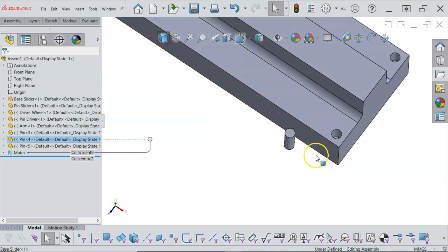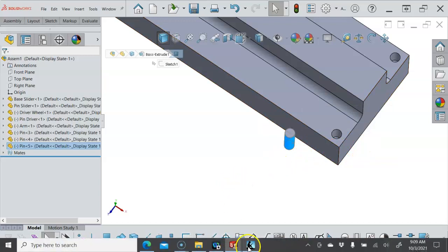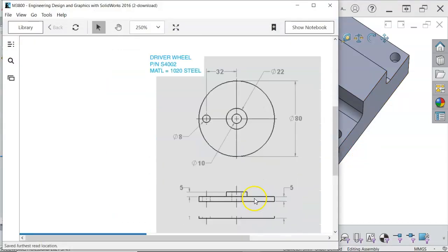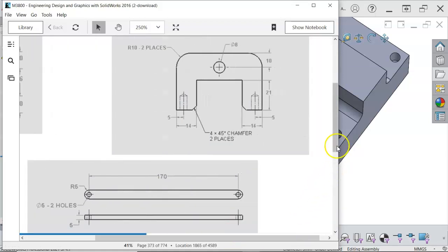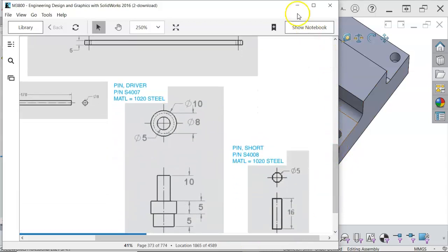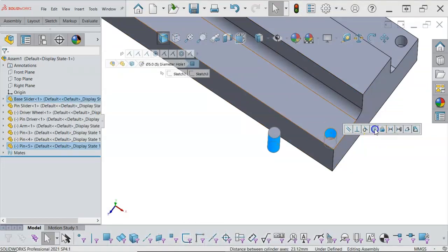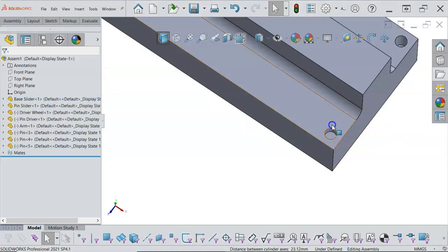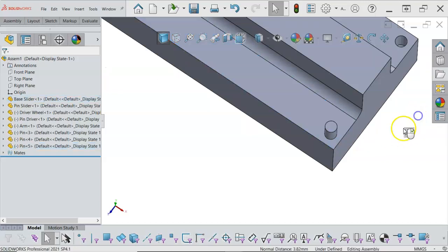Try to find the bottom of the hole. Let's see if we can, we'll do a different style. Let's see, how long was this pin? Should have just measured it. So 16 millimeters. So if I wanted it to be centered, we can go concentric, and then that'll be a good use of the flip dimension. So if I Control Select and go into the distance, 8 millimeters would be half, but it went the wrong way. So we have this flip dimension that will bring it back up.